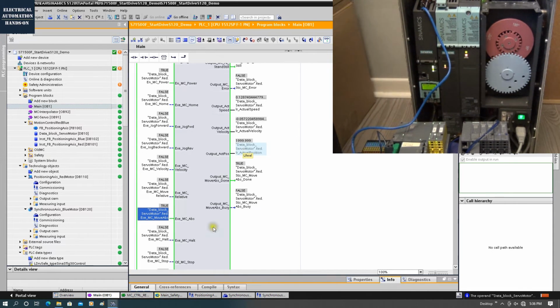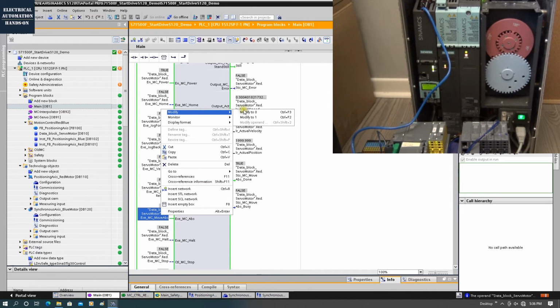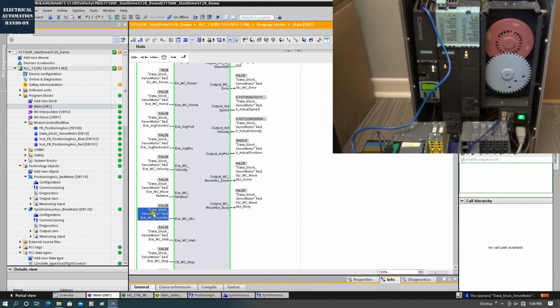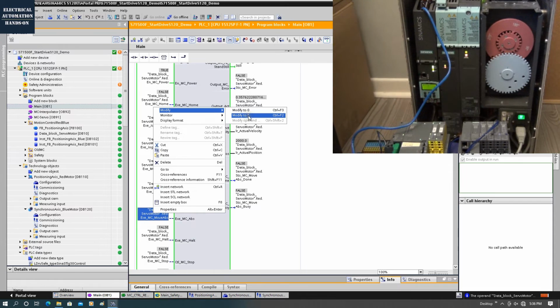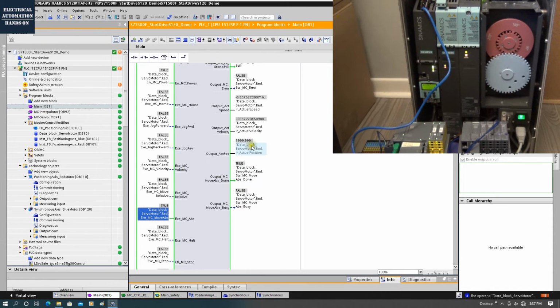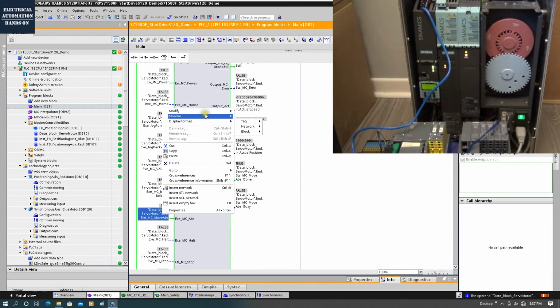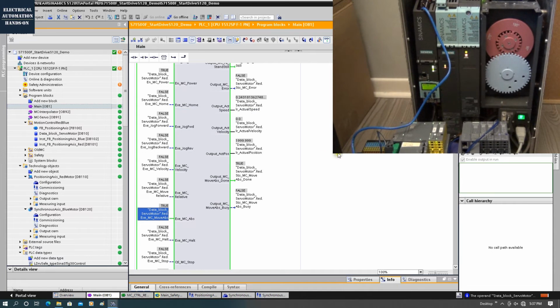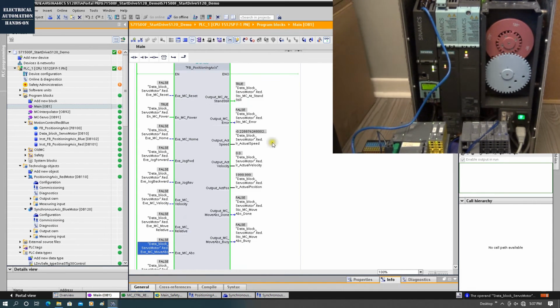Okay, it drives to 2000 because this is an absolute position move, and if I trigger again, the motor won't move because it arrived at this target. If the target doesn't change, even if you trigger it again, it won't move. Okay, it stopped here. It shows standstill on.